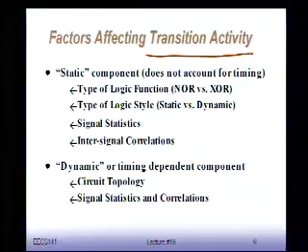It's also a function of the signal statistics. If I have an input waveform where there's not much happening, like for instance, I take a little filter of your project, and I apply a very tiny sinusoidal input. Very tiny. It only switches a couple of bits. Most of the MSBs of your filter will never do anything. On the other hand, when I apply a large waveform that goes back and forth real quickly, a lot of activity will happen. You will see a lot more switching activity. So the input waveforms have a big impact on the overall power dissipation.